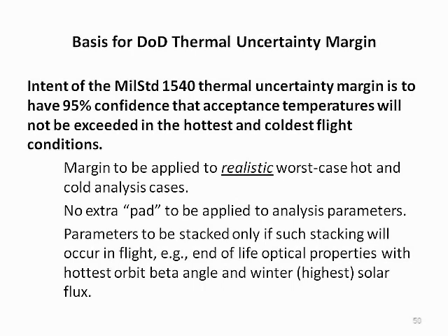The intent of the 11 degrees C analysis uncertainty margin required by MIL Standard 1540 is to have 95% confidence that acceptance temperatures will not be exceeded in the hottest and coldest flight conditions. This margin is to be applied to realistic, worst-case hot and cold analysis cases with no extra pad applied to analysis parameters. Parameters are to be stacked only if such stacking will actually occur in flight.